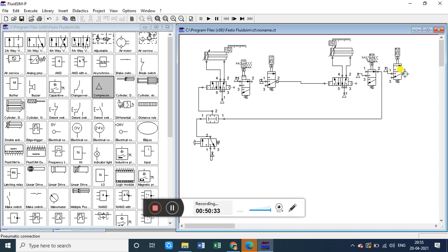2s2 will get pressed. From this 2s2 we must give supply to this side, so that this line will give compressed air inside the cylinder from the right hand side, and this will exhaust the air into the atmosphere, and you will get a retraction for this cylinder.